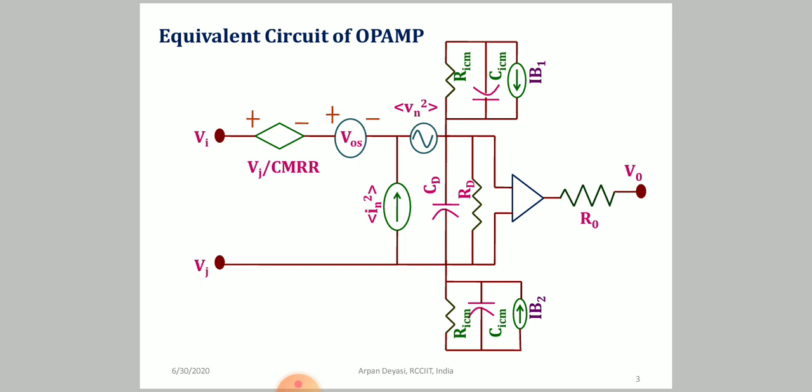And you will find there the discussion about the virtual and actual ground and the differential input. Naturally, if you have two MOSFETs, their thresholds may not be exactly the same. Their aspect ratios may not be exactly the same, and in the last part of this lecture I will discuss the design of the aspect ratio, or the choice factor, and how it critically depends on the other specifications. And the two RD resistances: while you are making an integrated circuit, you can't say that the drain resistances are exactly the same. So there may be an offset null sort of thing,